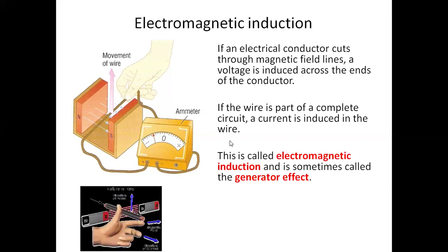And the direction of induced current is found out by Fleming's right hand rule, where the thumb shows the motion. Here the thumb is pointing in the upward direction because the wire is moved upward, the field is from north to south, so the current is outward.